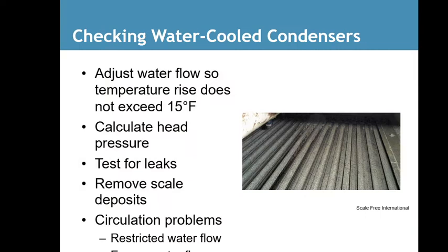Checking water-cooled condensers. Adjust water flow so temperature rise does not exceed 15 degrees Fahrenheit. Calculate head pressure. Test for leaks. Remove scale. Restriction problems. Restricted water flow. Excess water flow.